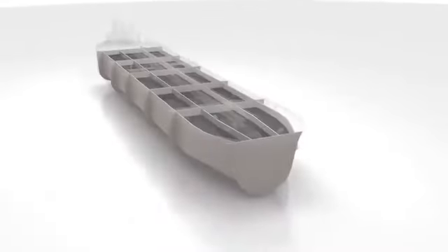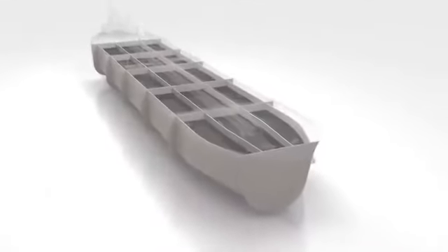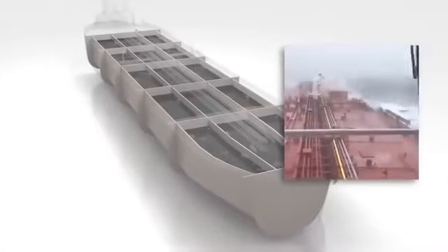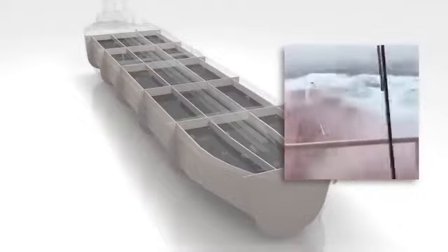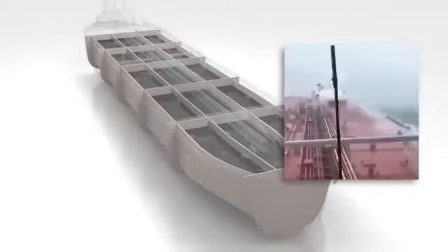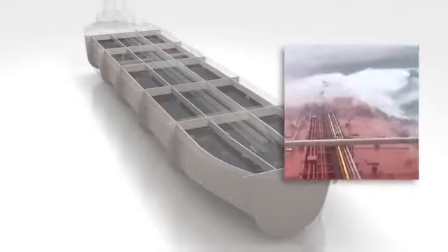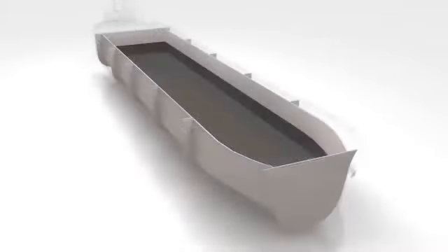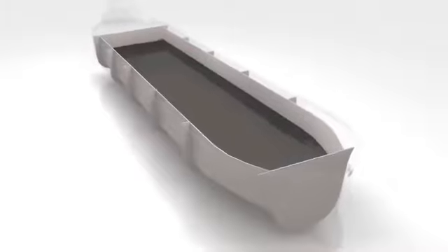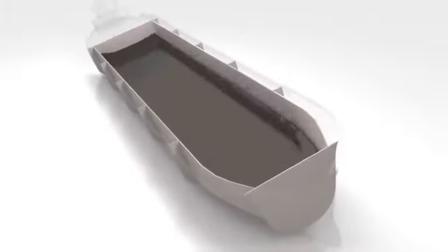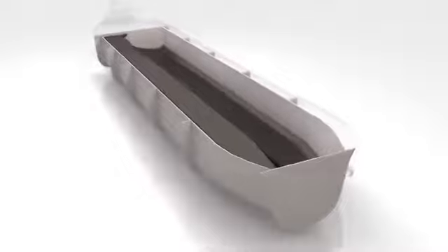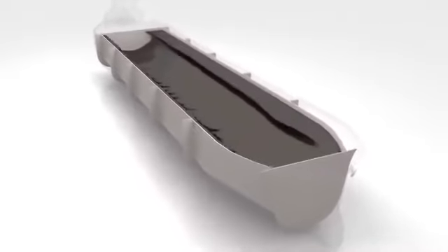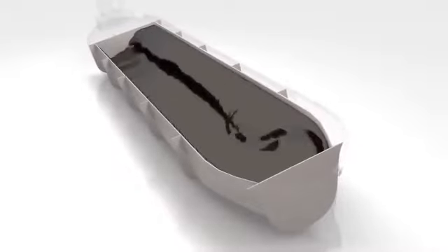A large crude oil tanker has multiple oil cargo tanks, primarily to avoid free surface effects. Sometimes the sea can be rough, just like in this scenario. If an oil tanker has only one giant tank to carry oil cargo, it will face free surface effect. When the liquid inside a tank moves from side to side, it generates forces that impact the side of the hull.